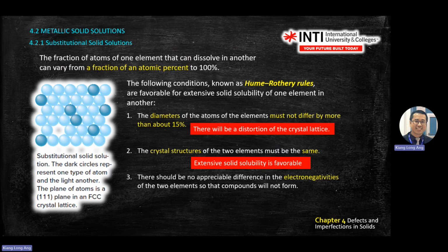So when we do substitution using the Hume-Rothery rules, we rarely take group 1 and join it with group 7 because you have a chemical reaction there. We don't want that. We only want to stabilize things. Normally they are quite near, for example in their own family. Electronegativity is also linked with the s, p, d, f orbitals on the periodic table because of the energy.